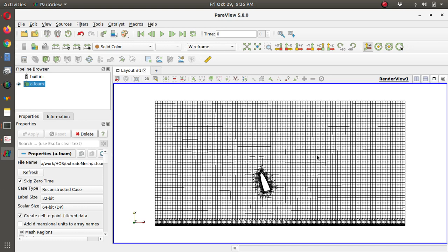make the mesh. But the requirement for the simulation of impinging jet turbulent flow using large-eddy simulation with volume model, the requirement of mesh is very dense mesh. So we have already made the dense mesh and simulated the case using OpenFOAM. We are not going to use this coarse mesh which will not give the accurate results.